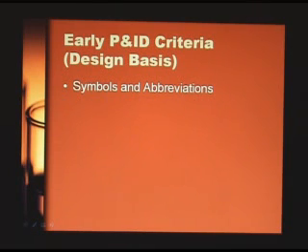And then piping prepares the tie-in list. Process engineers, if necessary, will add process data to it, or just verify that the process data has been properly interpreted by piping. And then piping will provide tie-in packages for every tie-in that there is in the plant, describing what needs to be done, whether it's got to be done on the run or when the plant is shut down, before the shutdown, after the shutdown. Some tie-ins require doing it while the plant is running, and there are special precautions to be taken. So all of this is done by piping.